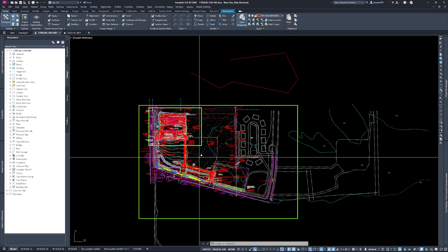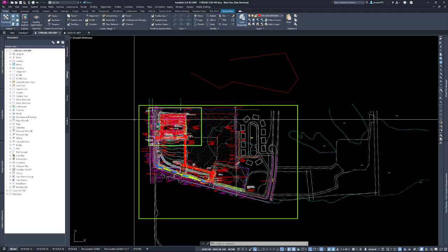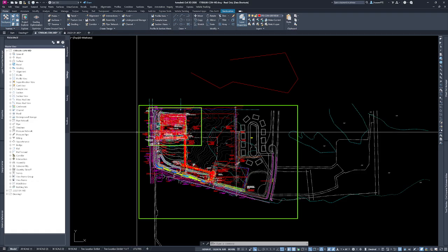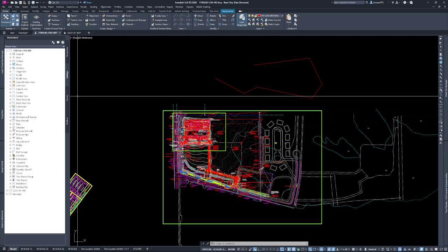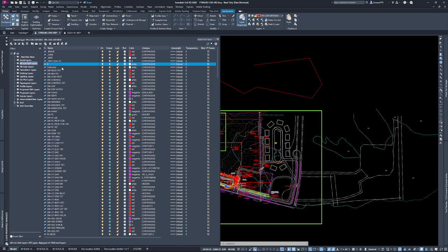That was something I wanted to show, because right now I'm working with files from four different companies on one project. I don't want to bring all their files in because I've noticed that they don't always match layer configurations. They don't always square in their drawings, but I need to have that information in my drawing so I can reference it. So bring the drawings in on the proper layers, even if you have to make a separate layer.